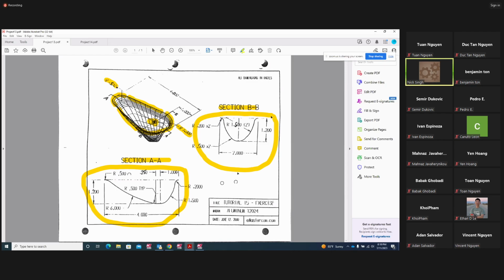This one here, we're going to create arc polar, this radius 1 inch. Then I'm going to create arc. The center point of the arc is going to be 4 inches. This is half. So it's going to be 3.5.